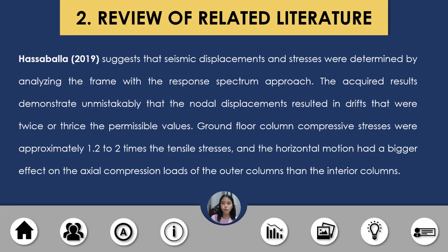Ground floor column compressive stresses were approximately 1.2 to 2 times the tensile stresses, and the horizontal motion had a bigger effect on the axial compression loads of the outer columns than the interior columns.